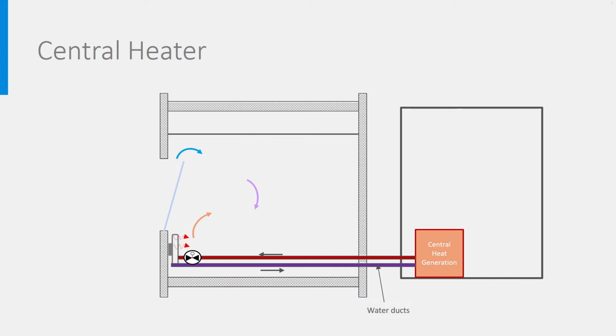Let's make a non-exhaustive inventory of these systems and start with a common house system in European countries, using a room that you see on the left. On the right we have the technical room, located on the roof or the basement, for instance. There is natural ventilation and a radiator connected to the central heat generator, generally a gas or wood pellet boiler, generating hot water that is circulated to the radiator, in which it cools down and then goes back to the boiler in a closed loop.